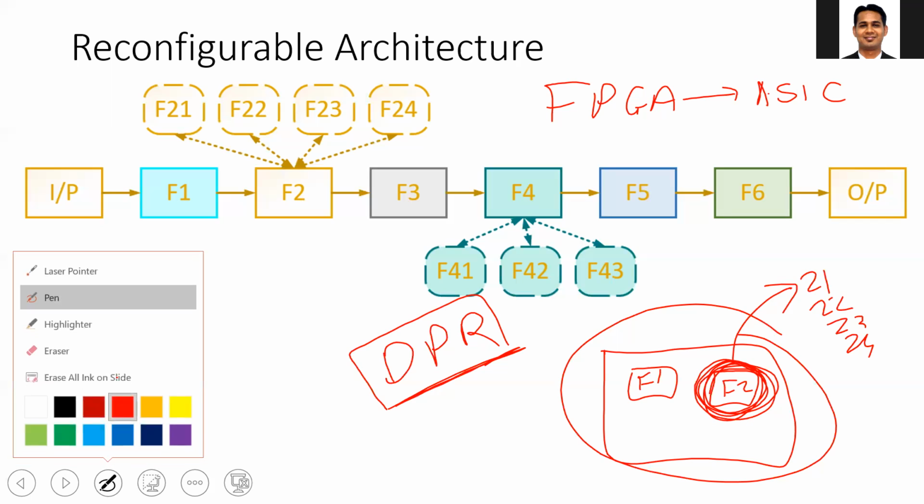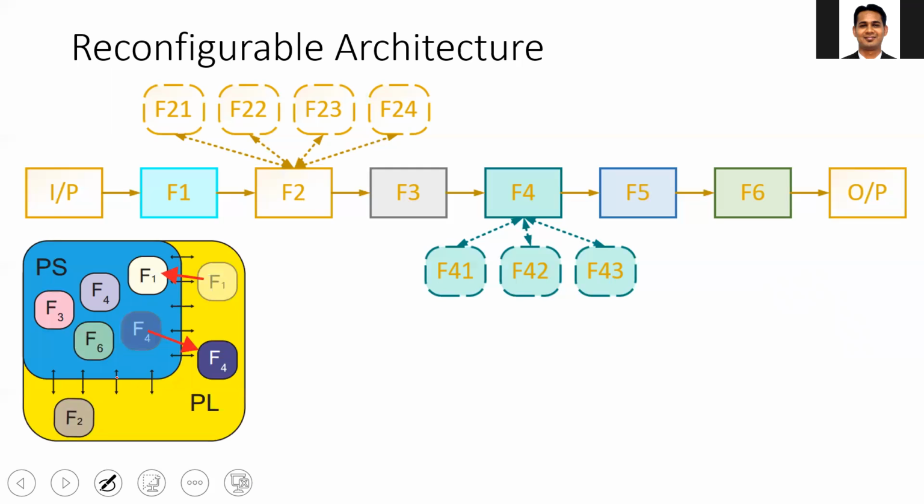With the reconfigurable features, hardware software co-design also needs to consider, when you move something to the FPGA, whether you can exploit the reconfigurability. If not, then you should use the ASIC, and the FPGA doesn't make sense. FPGA makes sense only when there is a reconfigurability feature. If you are using FPGA for an algorithm where there is no reconfigurability, you are wasting a lot of money, and your area and power consumption will be higher than the ASIC.